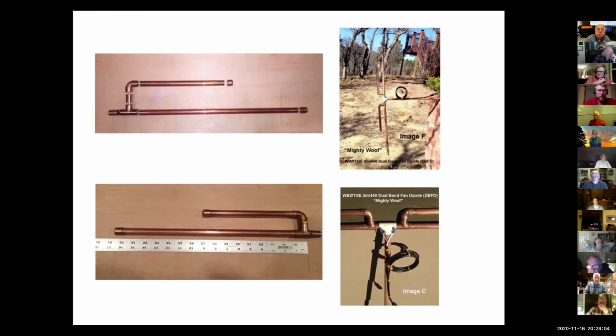When you're putting together copper antennas, the important thing when you're soldering is to make sure that you clean it using a wire brush or steel wool or something like that. And you use flux in this antenna. I know in electronics, you want to make sure that you use the right kind of flux, like with rosin core and all that stuff. But this isn't like regular electronics. This is like plumbing. So you just use regular non-lead solder or lead solder to assemble these things.